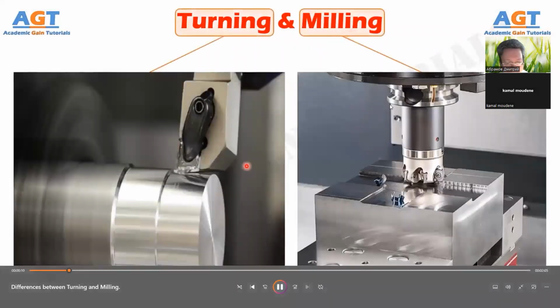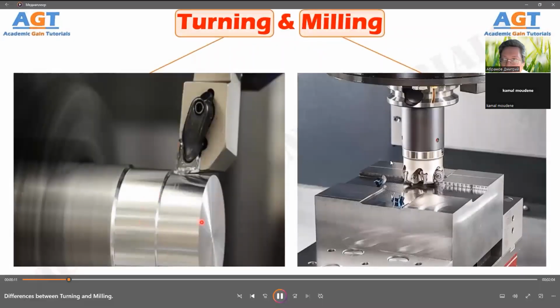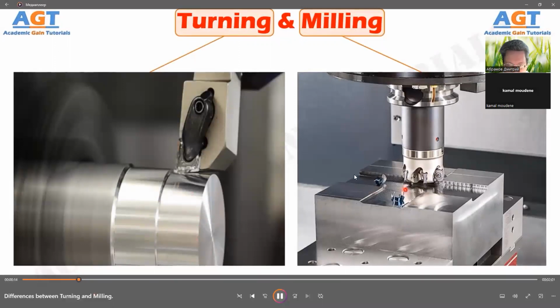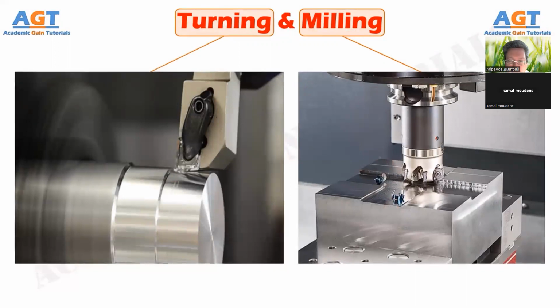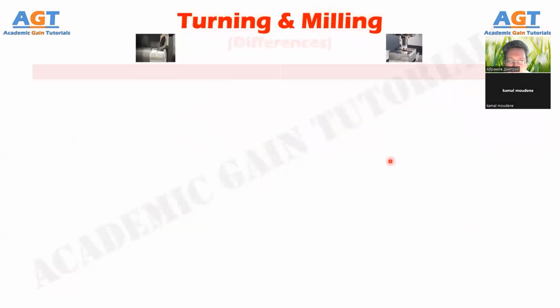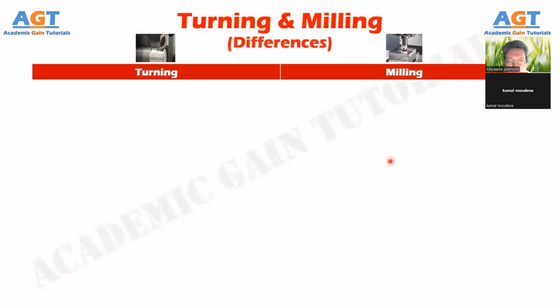Conventional machining is one type of manufacturing process in which excess material is removed from a preformed blank by shearing in the form of chips using a wedge-shaped cutting tool in order to get desired shape, finish, and tolerance. There exist several machining processes to efficiently machine a wide variety of materials in innumerable ways. Turning and milling are just two examples of such machining processes. So, let's look into the basic differences between turning and milling processes in a tabular form.